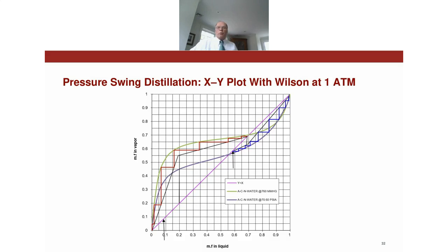So for the acetonitrile water separation, this is a McCabe-Thiele diagram that demonstrates how it works. The low pressure column is demonstrated here using the green colored VLE data. So basically the feed comes in here, and we're easily able to strip the acetonitrile out of the water to get down to a very low concentration of acetonitrile in the low pressure column.